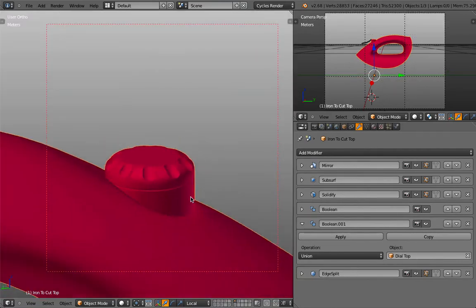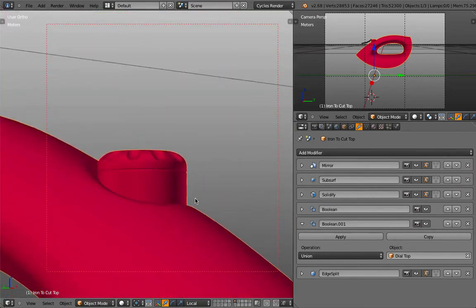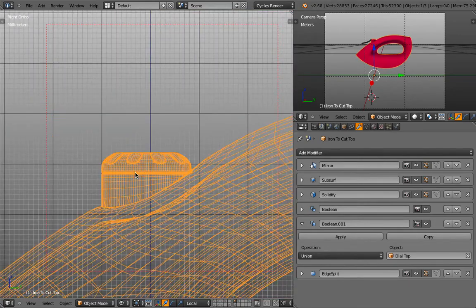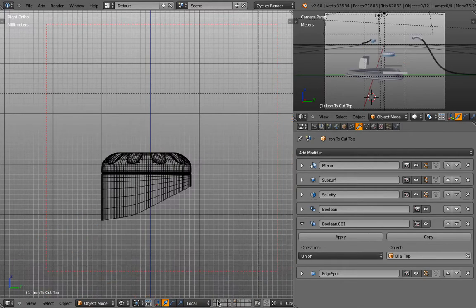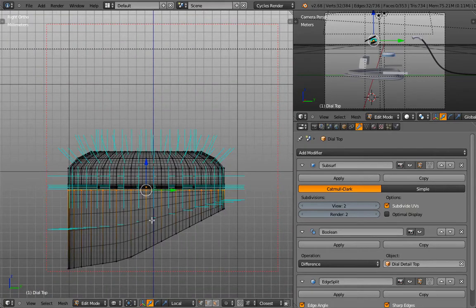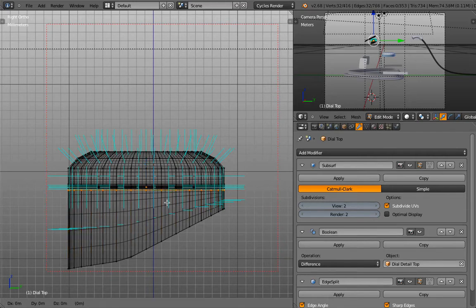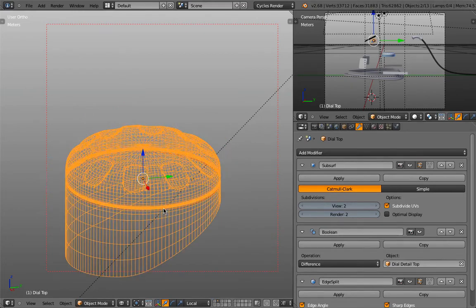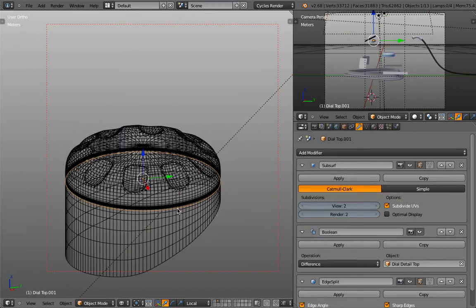Now there's only one tiny problem left. The button is solid, and you see there is a hole. So what we're going to do, we basically will create another cylinder which we can stick in and just simply cut out. So to do this, I go to this part, and I'm actually duplicating with Shift-D a loop, press P to separate it. And by having that mesh separated, you see it's now an object on its own.